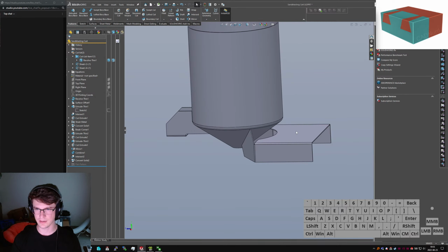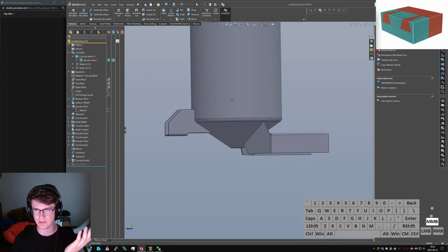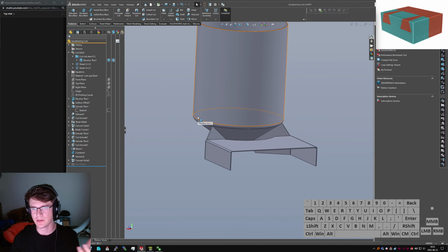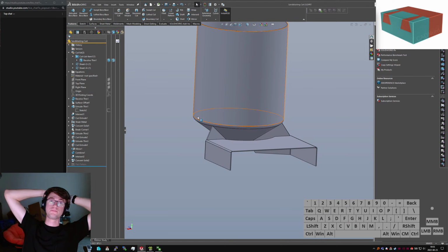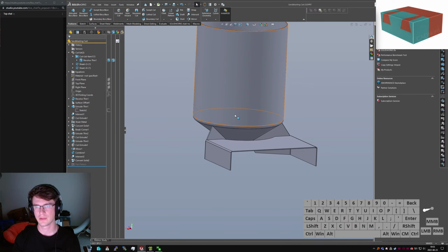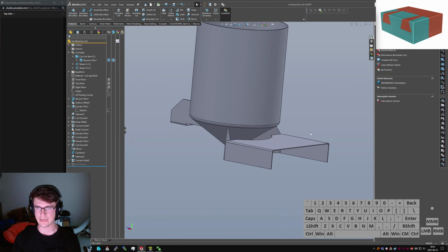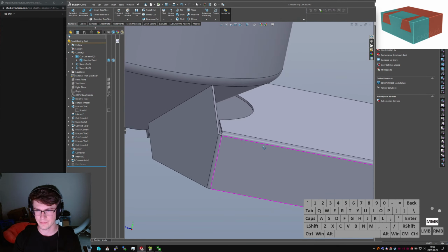I don't think I have any other clever things to answer here. Just careful use of the intersect tool. If you have a complicated sheet metal part, potentially starting with a thin extrude is a great way to reduce the complexity and silliness of trying to manage and bring things up to edges, because that won't let you use more complicated tools that give you a little more control, like intersect. So, something to be said for that.